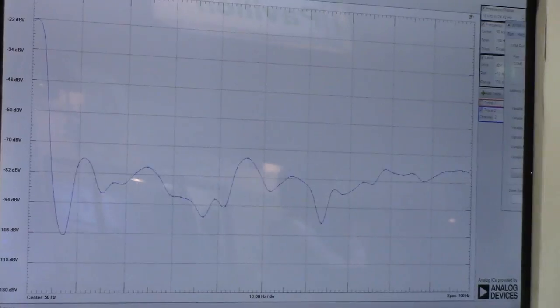And torque ripple is quite important in automation drives because it indicates how well or how smoothly you're controlling the system. That'll affect quality. May affect the bandwidth that you can drive the system at. So you want a low torque ripple. And it turns out the way you measure the current in terms of how you sample it and the offset in the converters can have quite a big effect on that torque ripple.